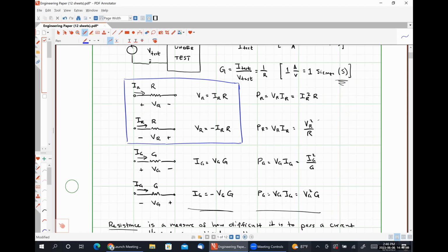So if we look at the circuit diagram that we were just dealing with, in one case for the voltage drop V30, our current was passing through the positive polarity terminal of our resistor, which is why I used this expression. When we were applying Ohm's law to figure out what was going on for the voltage drop Vx, the current IA was flowing into the negative polarity terminal, which is why I used this formulation.